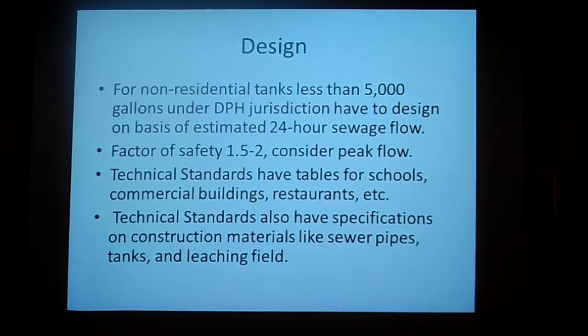For a non-residential tank that has less than 5,000 gallons, but is still under the Department of Health's jurisdiction, it has to be designed on a basis of an estimated 24-hour sewage flow with a factor of safety of 1.5 to 2. Also, the peak flow needs to be considered. There are technical standards published in the Department of Public Health documents that have tables for schools, commercial buildings, restaurants, and other things. Technical standards also have specifications on construction materials like sewer pipes, tanks, and leaching fields.